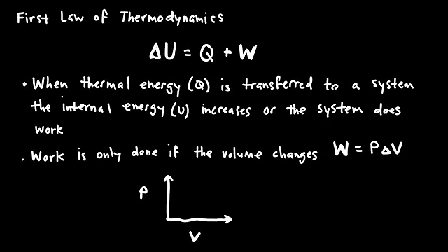One of the things that we know for sure is that the work that a gas can do has to be associated with a change in volume. And so we can calculate work in cases where the volume changes. One way that happens graphically is in cases where there's a constant pressure, but the volume is changing due to heat being added or something like that. Then we might get a graph that looks like this. And the area under that red line would look like this.